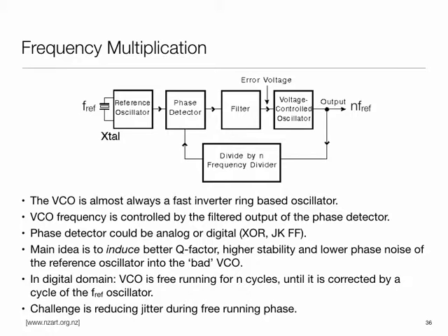So to summarize, the main takeaways are, number one, stability is the challenge. Rest of the stuff can be compensated for. So stability, you've got to pay for it either by power or cost or some combination thereof. Frequency: for a clock source within the same technology, higher frequency clocks are going to consume more power. So while the system is not doing anything, you probably want to dial down the clock, but that presents a challenge that when you're waking up, you're losing precision in wake up time.